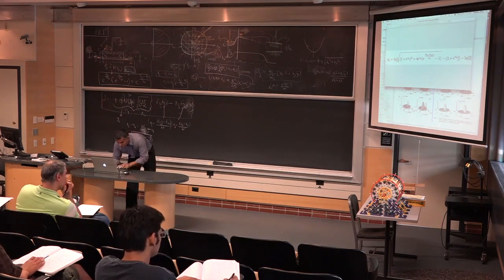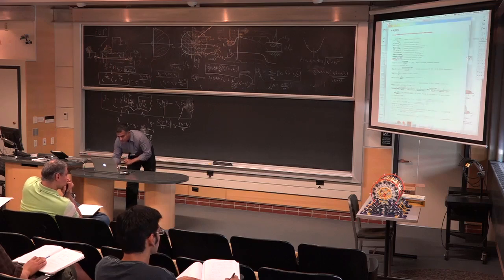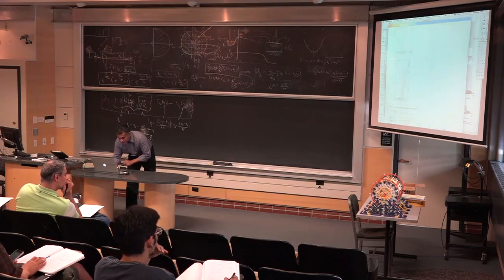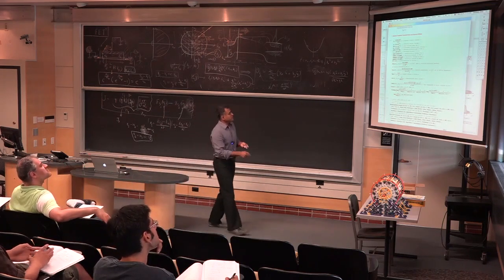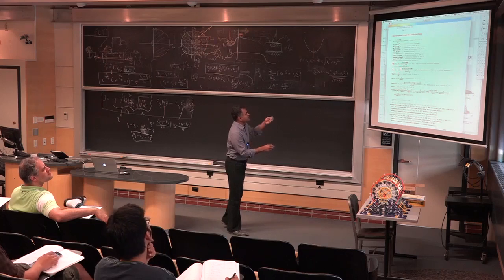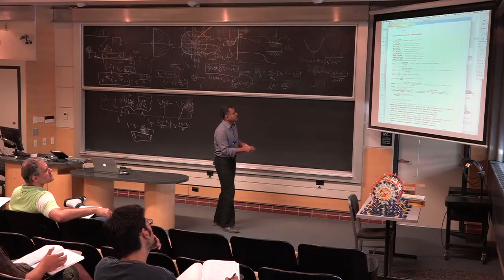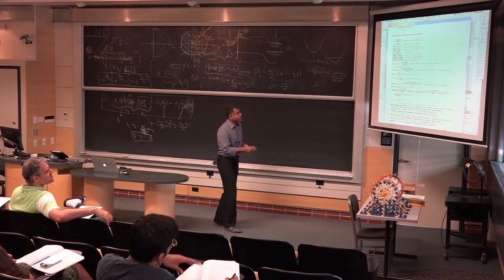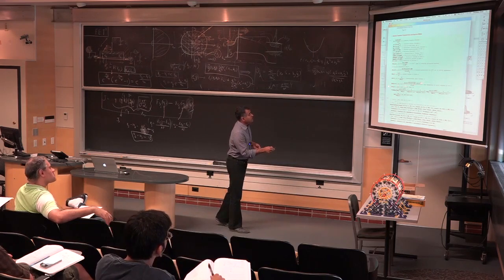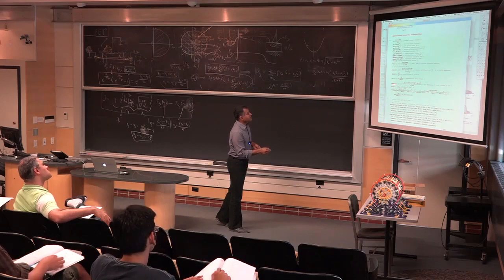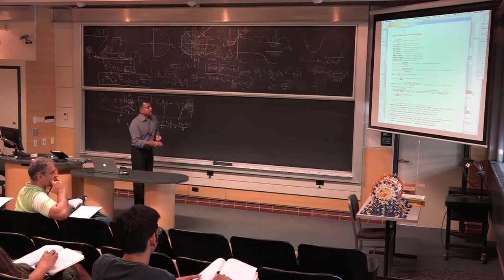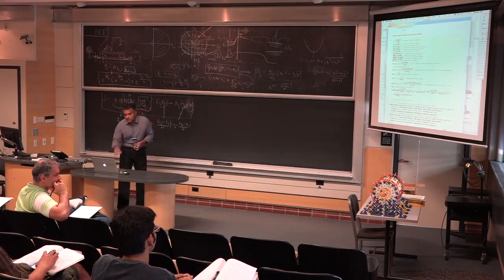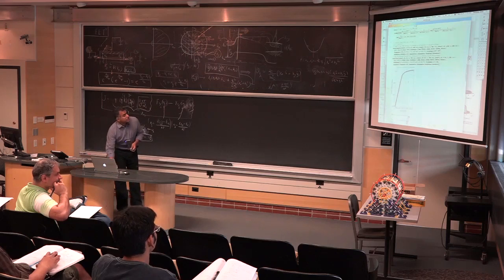And here's an example of some plots. Once you make the plot, okay, I already showed that one to you. So this is what I'm doing here. By the way, this file is posted, so you can actually look at it. I'm defining all these quantities: barrier capacitance, quantum capacitance, thermal voltage, V sub D, which is defined as VDS over thermal voltage. And here's my current. I'm defining it as this is the coefficient, and then I'm solving for NS as a function of VG, carrier density as a function of gate voltage, and then here's my carrier density as a function of gate voltage. I've already showed you that.